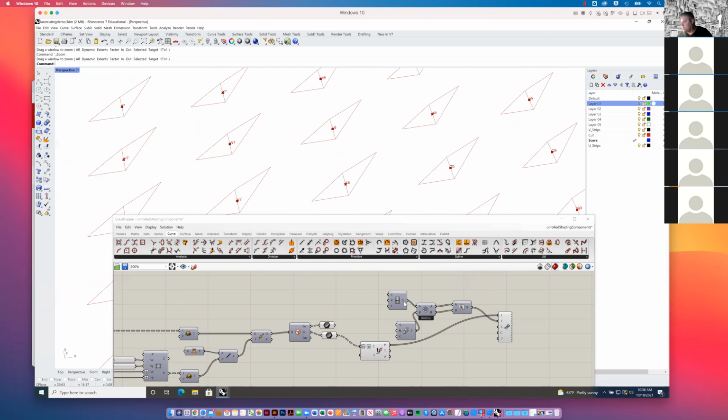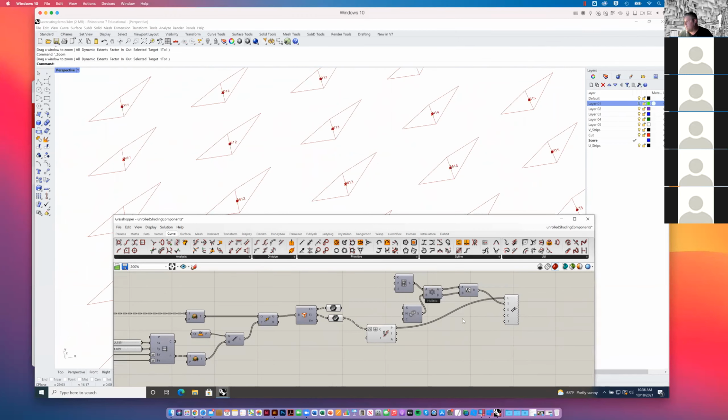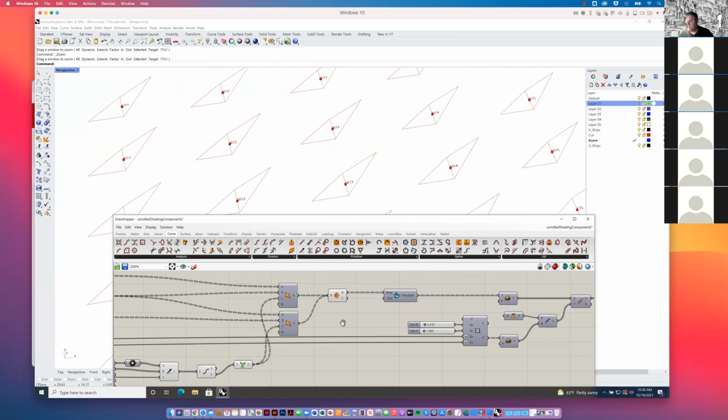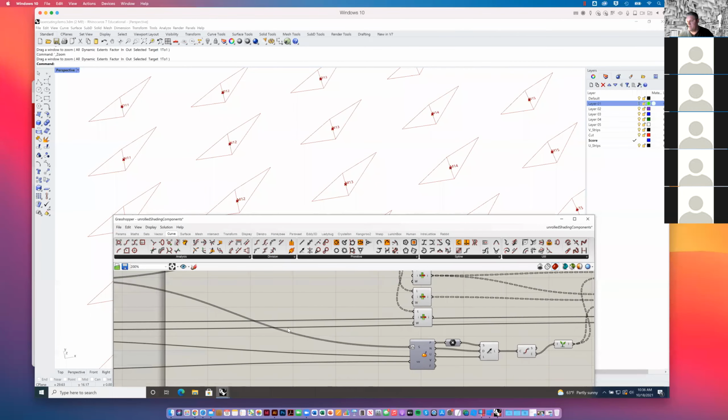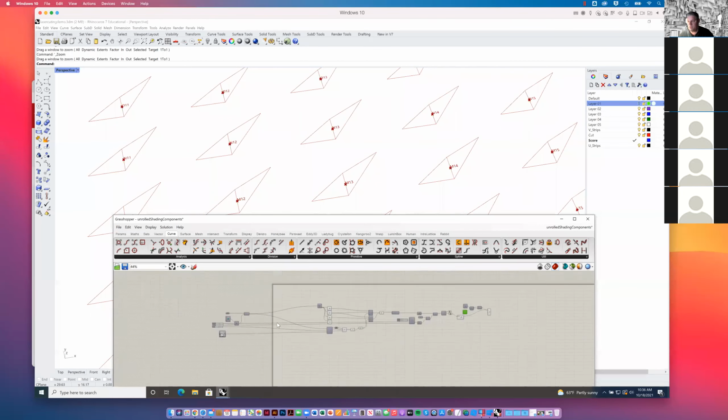Oh, I see. I guess you want to be very precise about this. So in this case, I would need 15 cells. That's how many divisions I had. And I'd also want to do that here, 15 and 15. So again, if you're going to use these label tags, you want to go back to, and understand how many cells you have, how many divisions you had, all the way at the very beginning, which again are those parameters that I told you to remember anyway.